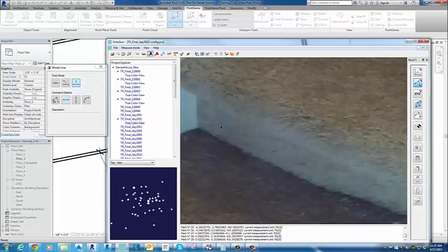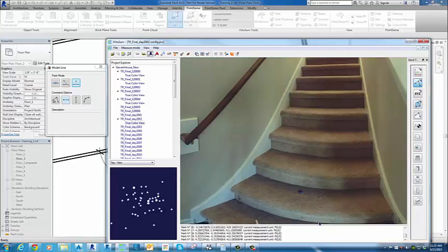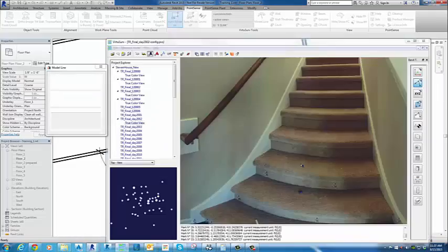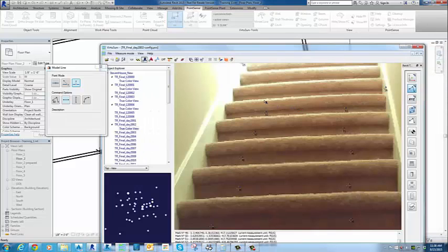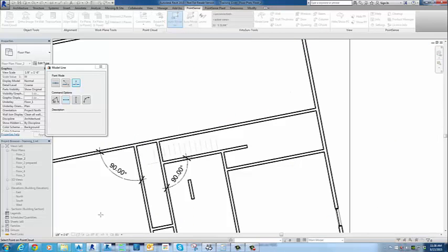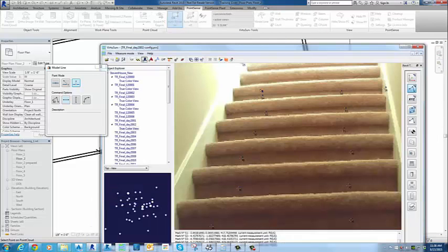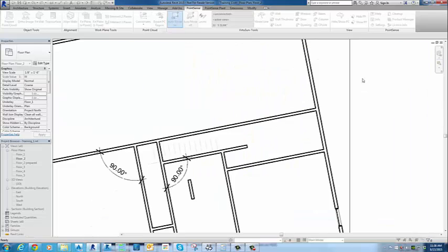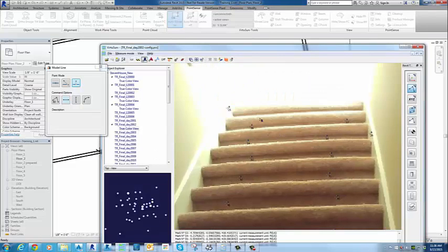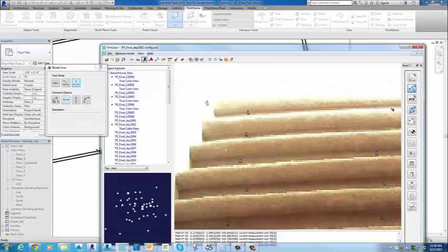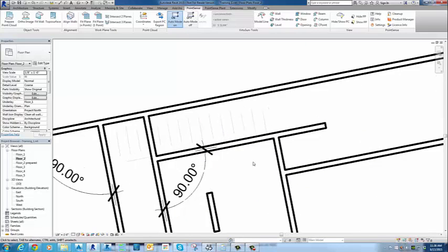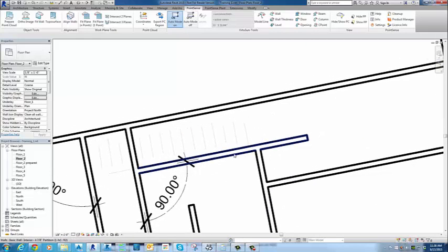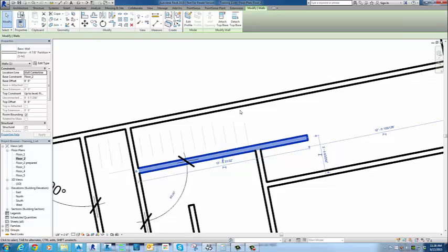and then I'll start placing individual segments for our risers. And I'll fast forward once I get going through here. So now I'm clicking up the stairs, 2 points on each step face, and you can see in the background, you'll see when I switch over that the line work is there.